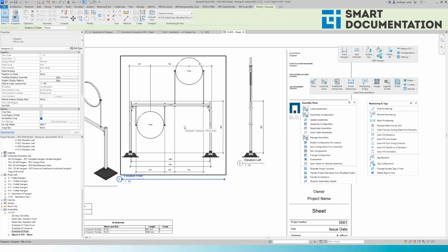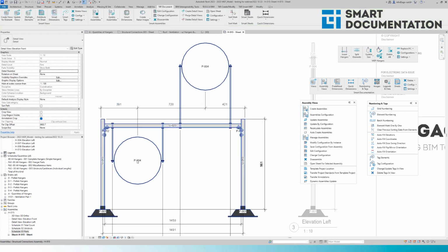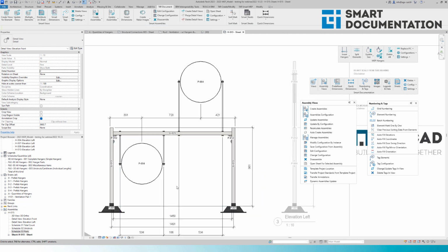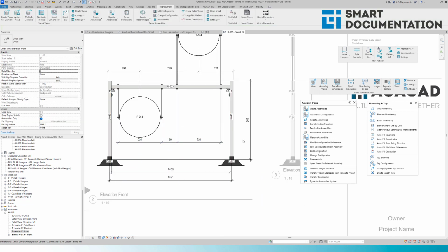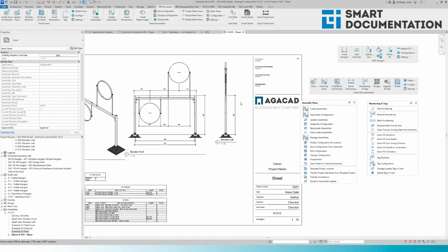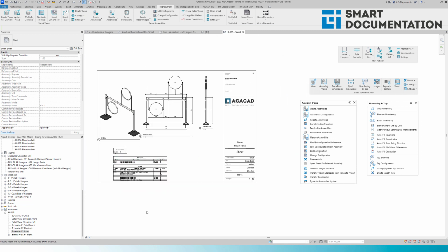And let's look at the dimensions that I have here. So at the top, I have dimensions for these hangers, and they're connected to the sides of the frame. Here I have a dimension for rods, and here again, Unistrut length for vertical Unistrut, for horizontal one, and distance between centers of the vertical Unistruts, and vertical elevation, and all the other good stuff.